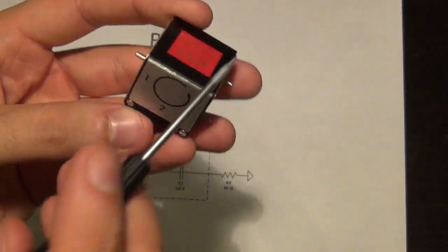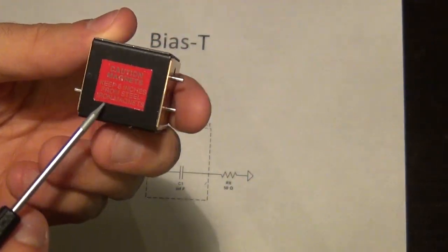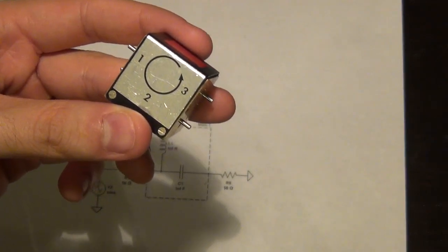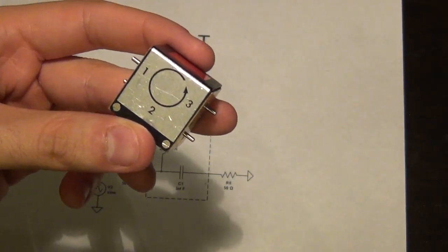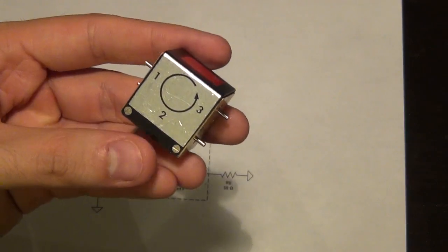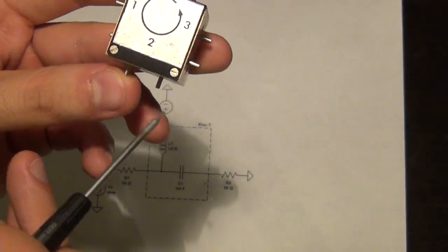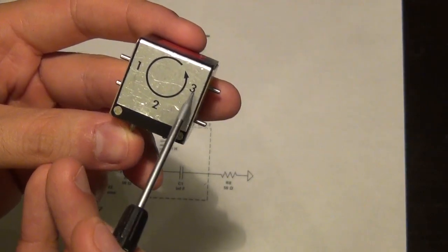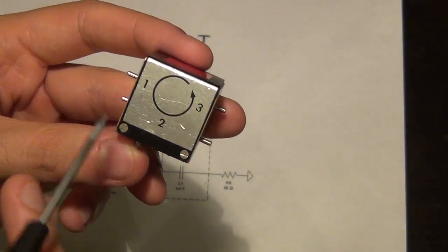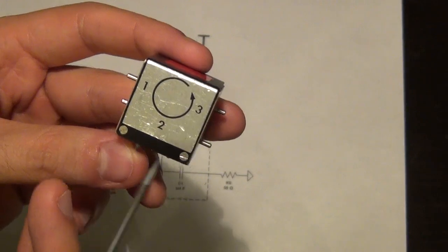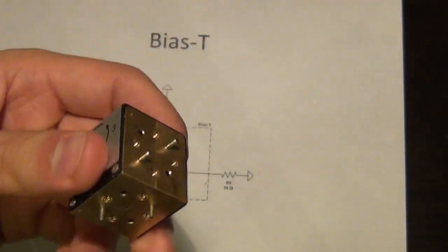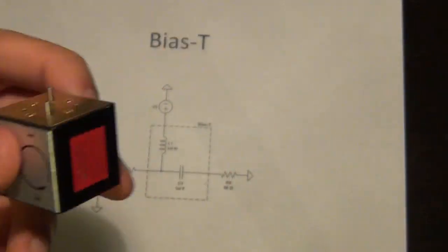So there's a magnet in here, and there's actually a warning here that says there's a magnet, and the magnetic field is designed to, I should say, guide the field that is allowed to flow through it. So this is port 1, this is port 2, this is port 3, and the signal can only flow in this direction. So the signal will only go from 1 to 2, from 2 to 3, but it cannot go from 3 to 2. So that's why it's called a circulator. Also a very useful component if you're doing some fancy measurements in waveguide.